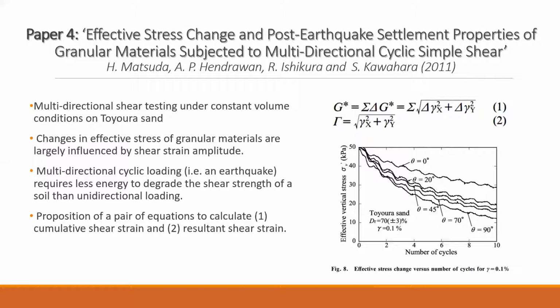Additionally, they proposed a pair of equations to determine cumulative and resultant shear strain in a soil, which have been used to investigate effective stress changes of granular materials under undrained cyclic shear conditions.